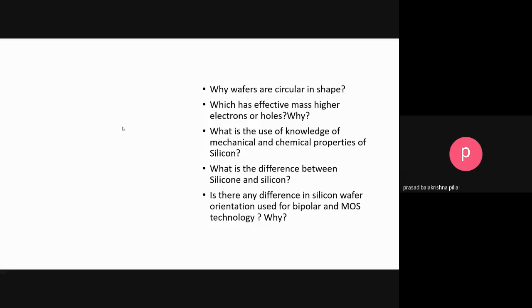But nowadays, because you have a system on chip, depending upon the application, for example, the SoC chip of a cell phone will be different from the SoC chip of your tablet or a digital camera. So the sizes are not fixed, because the packing density and the number of blocks in them are different. So it can be rectangular. Early days it was 1 mm by 1 mm, squares. But now increasingly it could be rectangular, and the sizes are also not fixed. So basically the wafers are circular because of the pulling process, the crystal growth process.